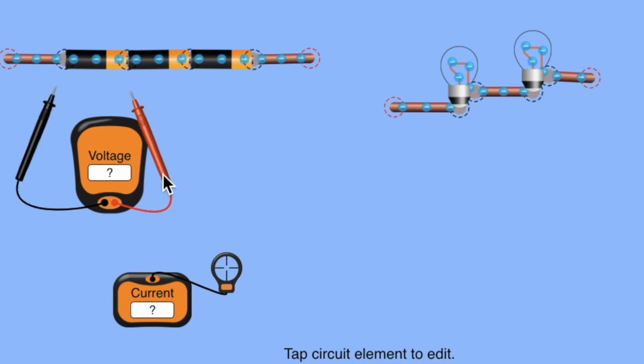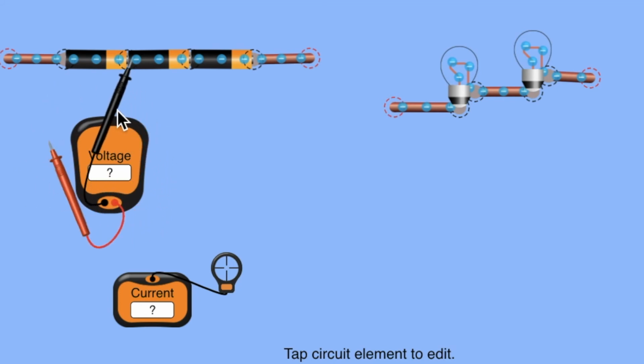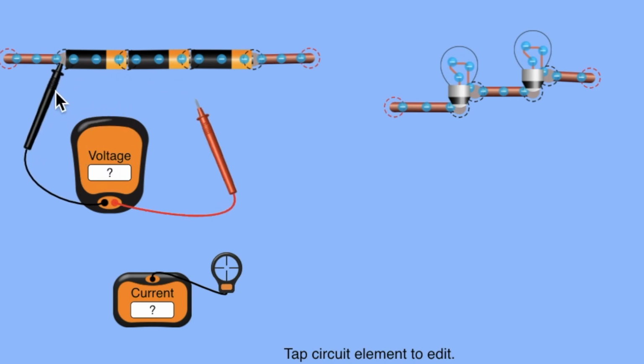If you ever come up with a voltage, and I'm going to purposely do this, and you have these leads and you get a reading that is a minus, a negative reading, that just means you have your leads crossed. Now in here it sort of works out that it works just like that, but you might have another part of the circuit that you're measuring, or the way you build your circuit, and you attach the leads to measure the voltage across either a battery, group of batteries, or some loads. And if you get a negative reading, that means you just have your leads flip-flopped and you just got to exchange the leads, or if you just want, just take away the minus sign, and that's the voltage reading there.